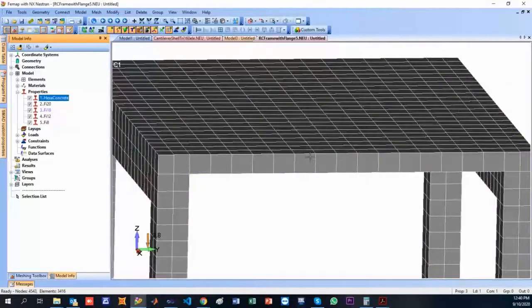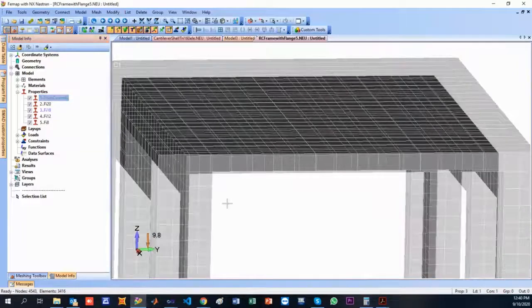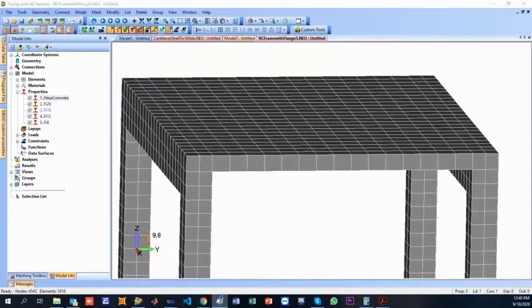Edge reinforcement. You have to place edge reinforcement at the free edge of the slab, right? Which is a U-shaped reinforcement, and it has to be placed here and there. But that will not contribute to the strength of the slab, because this is just to avoid spalling. Have you ever heard about it? Edge reinforcement? Yes, no? Sounds familiar.